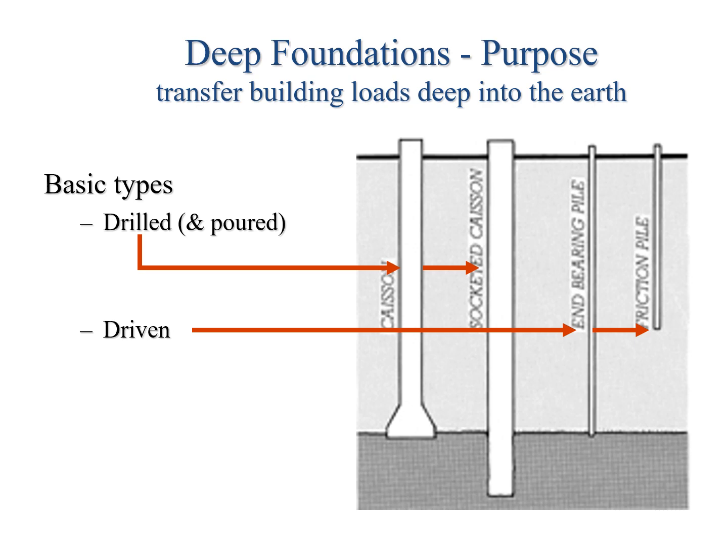So the deep foundations are where the caissons, those deep drilled and poured, as we saw earlier. That's that bell-shaped base, as it's sometimes called. Then a socket caisson has a straight-type bottom down below. The difference in color on the bottom is a different strata, mostly rock. The bell shape is sitting on that type of rock and pretty much distributing the load. That's why you have that wider portion down at the bottom.